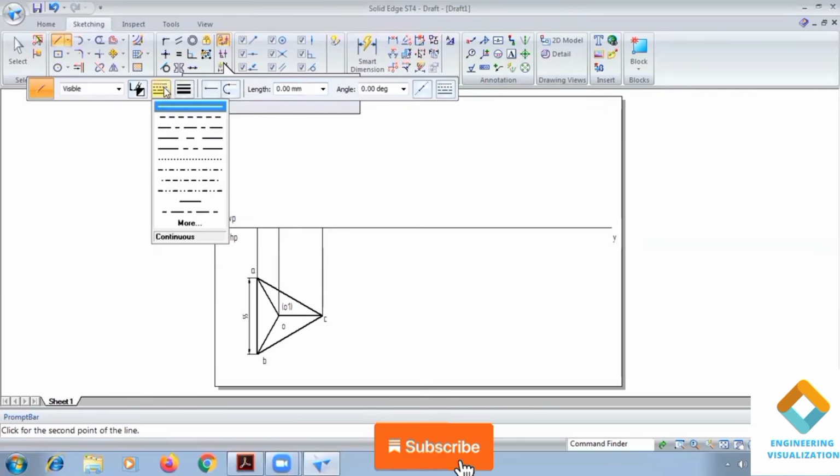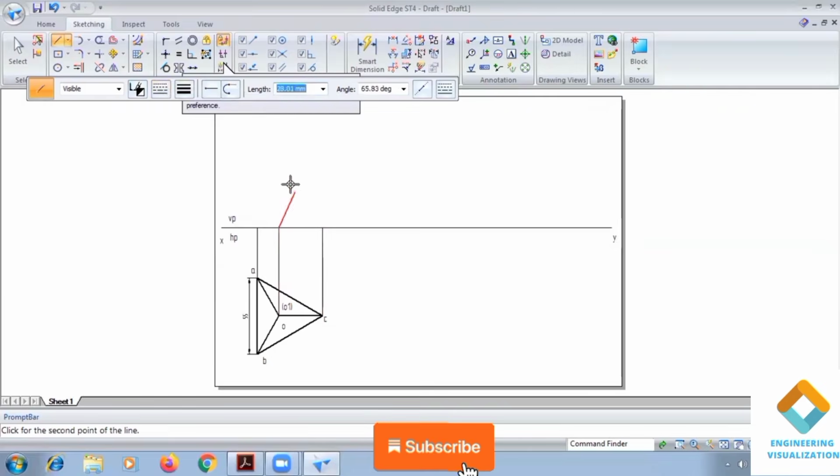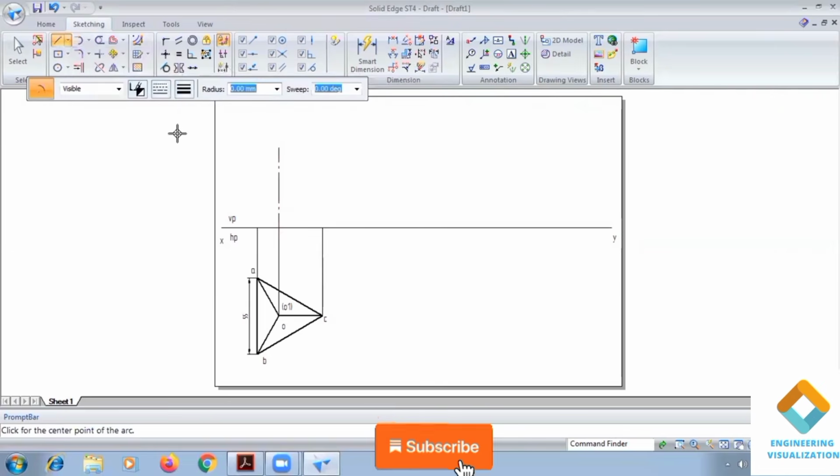Okay, in this problem we don't know the axis length; this is the tetrahedron problem. Just randomly draw it, and from one end, which is parallel to x, you can see CY is parallel. That's why we are cutting the arc from this end with a length of 55 mm radius. Cut the arc. Okay, now join it.